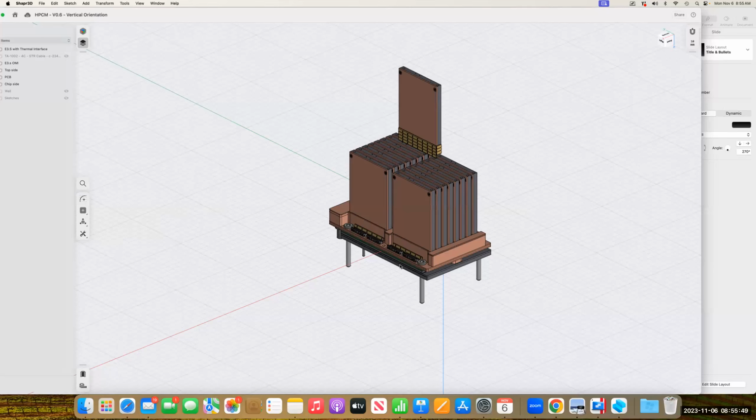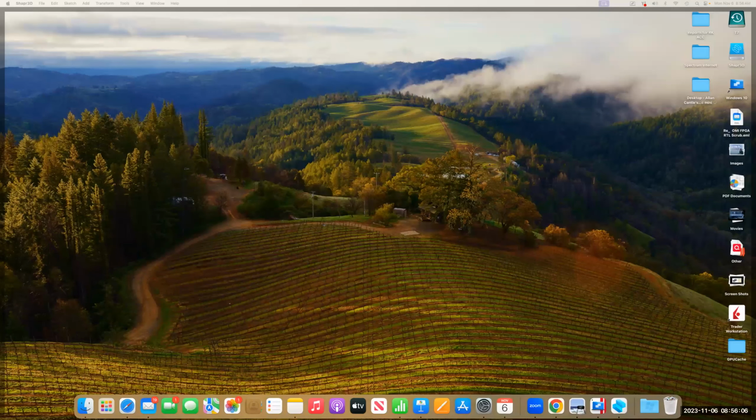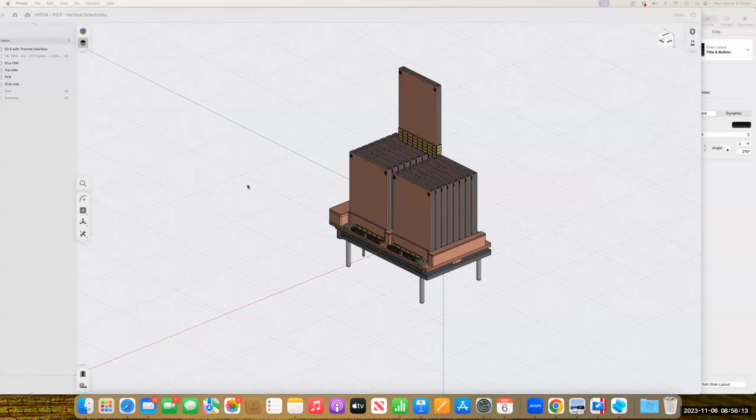We don't want to damage the SMT solder joint, and we want force relief on those board locks. So if your frame works very well, and if any deviation from the normal position, the frame will provide the force to control the card position, then I think it has a good chance we can try the SMT, but still, at the end of the day, we need to do the test, right?